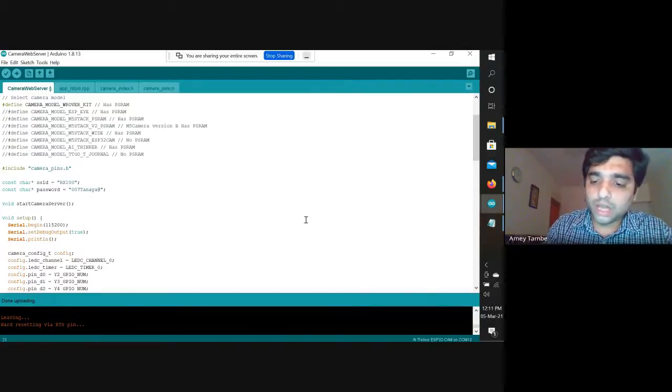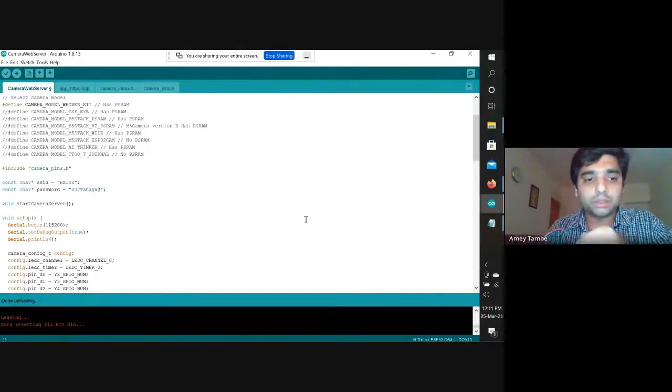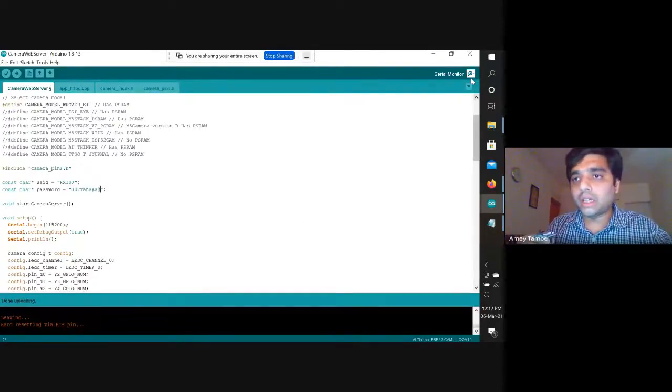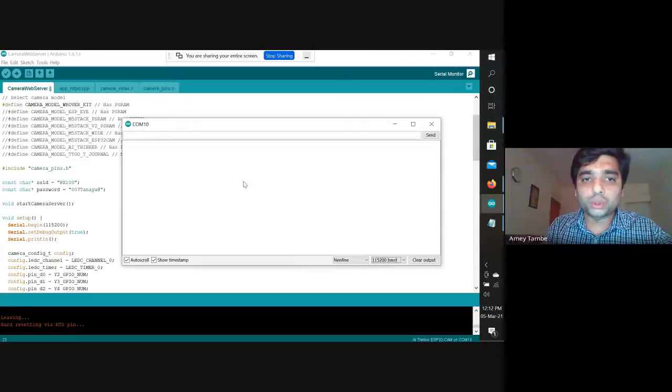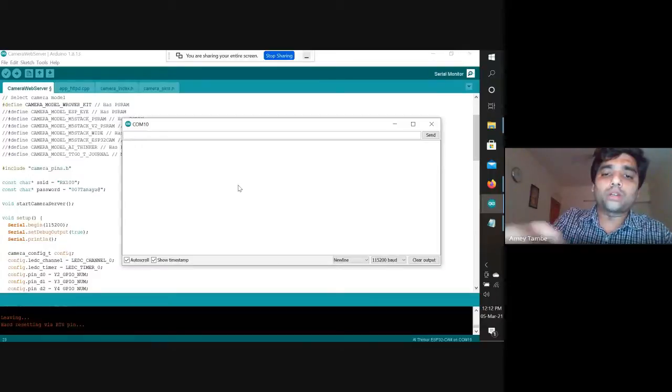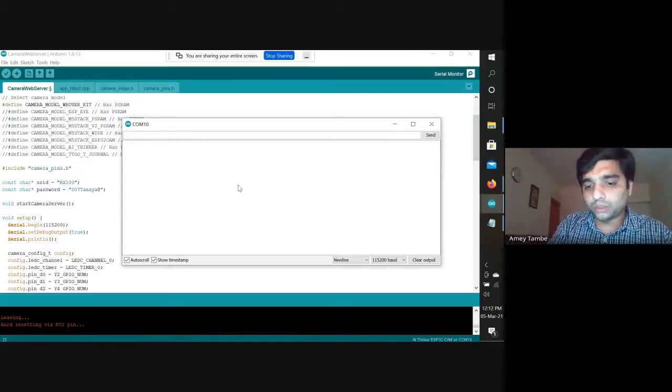Okay, now this is done. I'll click on reset tab. So reset tab is behind it here. I'll just press it once. Once I press it, it will turn on a LED and turn it off again. I'll open up my serial monitor. I'll go to baud rate of 115200. Now here I'm supposed to get information. Before that, the loop what we have created, we need to remove, because this loop is only required to program the board, but to operate it this loop is not required.